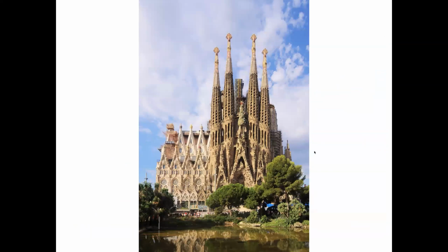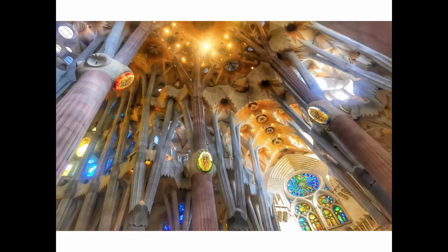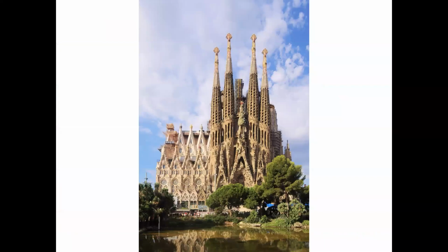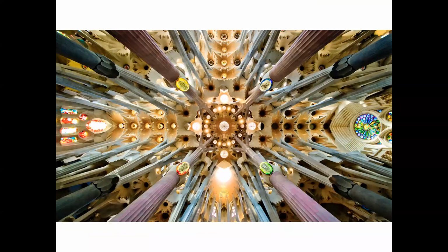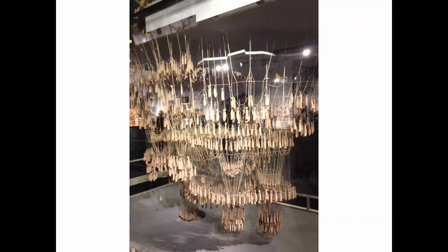You could also do form finding. Grasshopper with a plugin called Kangaroo will let you build in a physics engine. I refer back to Anton Gaudí in Barcelona. I don't know if you guys have been to Barcelona and seen the Sagrada Familia, this beautiful cathedral that's actually still under construction to this day. It's famous for these hanging chain models, looking at parabolic curves and approximating them by using gravity. So this is basically a structural model of the cathedral hung upside down to use gravity. Then you would freeze these with plaster and turn them right side up to get the geometry that's needed to withstand the gravity loads, right? Sort of catenary curves.